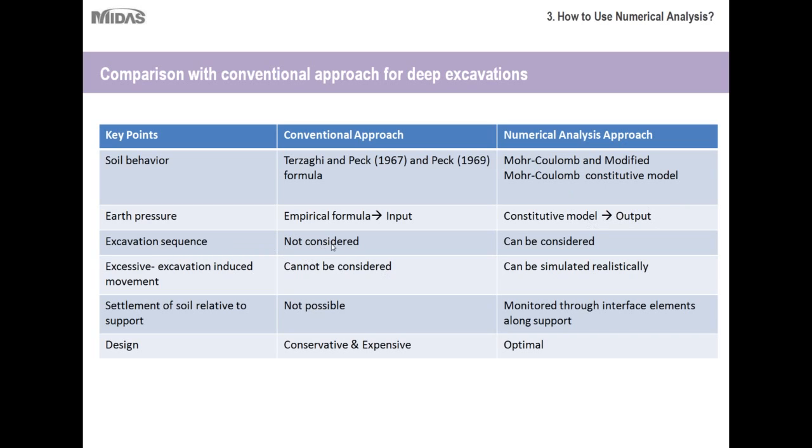Excavation sequences can't be considered in conventional approaches, whereas they can be considered in numerical analysis. So once again, for larger scale, lengthier projects where you have detailed construction or excavation sequences, numerical analysis is your only realistic option. Excessive excavation-induced movement can't be considered with a conventional approach. However, it can be considered and simulated very realistically with numerical analysis. That's another one of its strengths.